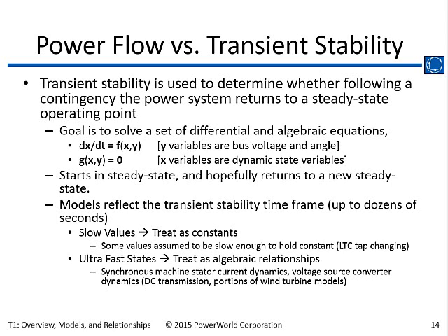I had one of my engineers who works in the EMTP arena using something called RTDS. He was comparing it between RTDS, which is a fast simulation, and PowerWorld, and he thought if he just put a small enough time step into PowerWorld transient stability, he would see the stator transients. He didn't see them because they're ignored. And then, if things are slow enough, they're held constant.